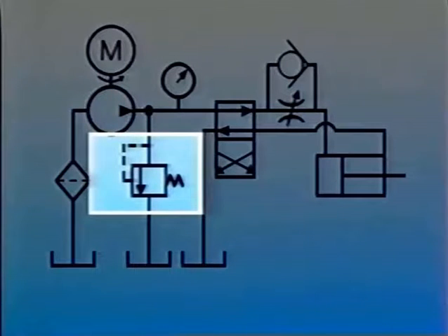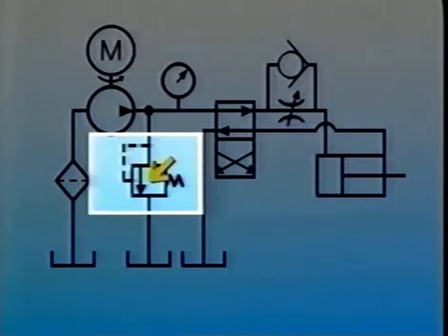This is the symbol for a pressure control valve. It includes a representation for the normally non-passing spool and the spring which biases the spool in place against the end of the valve. Notice the pilot line and the symbol for this valve.